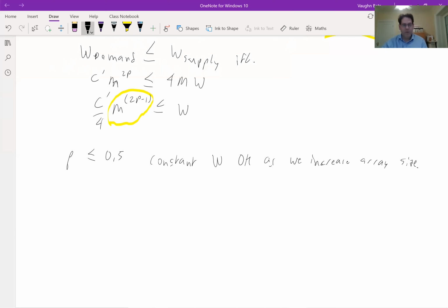So for circuits with good locality, island style FPGAs are extremely scalable. Just keep stepping out the same pattern of logic block and routing, and they route fine. But obviously, a Rent exponent of 0.5 definitely exists. It's not that rare, but they're nice circuits. There are lots of circuits that have higher Rent exponents. I talked about random logic, so finite state machines, lots of complicated control, can be more like 0.75.